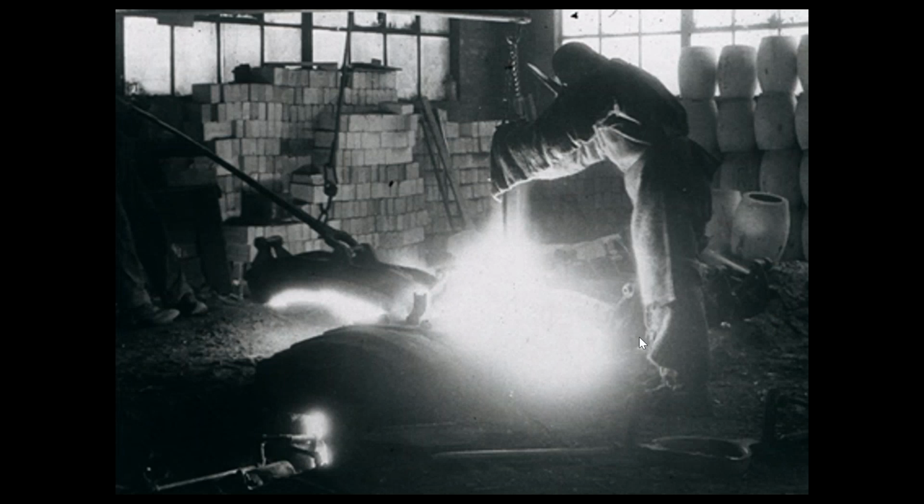Then in the mid-1700s, they discovered how to melt steel. And the way you melted steel was you took cast iron and melted it, because you could barely melt it with a really preheated furnace. And then you would drop in iron oxide. So you would reverse the reaction that you used to make the cast iron, where you took iron oxide and reduced it with carbon. And here you'd actually take high carbon cast iron and reduce the carbon with iron oxide, and you'd actually create steel by using iron oxide or ore to take the carbon out.